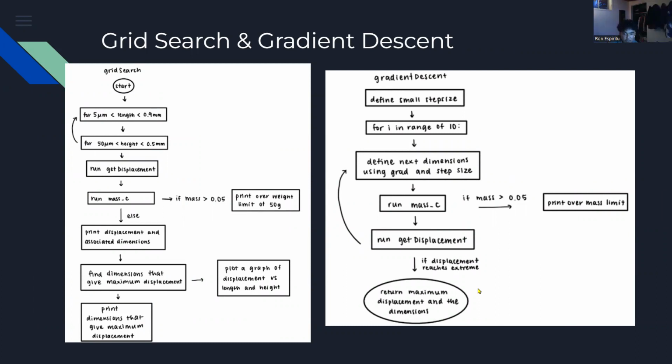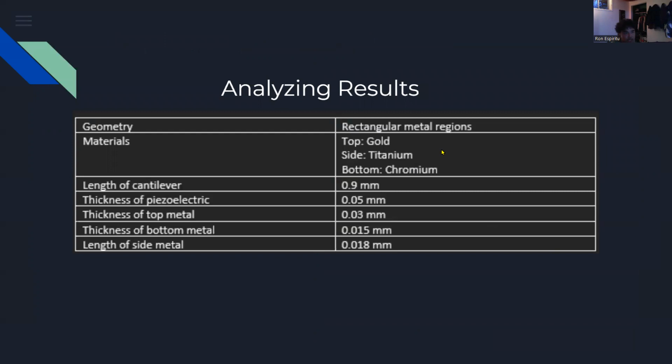The high length can be justified by there being a higher bending moment for higher lengths, and the high piezoelectric thickness can be justified by the desire for there to be a lower piezoelectric shrinking. This indicates that the thermal expansion heavily dominates the system's behavior. Also, the rectangular region is justified because this maximizes the amount of thermal strain occurring within our system.